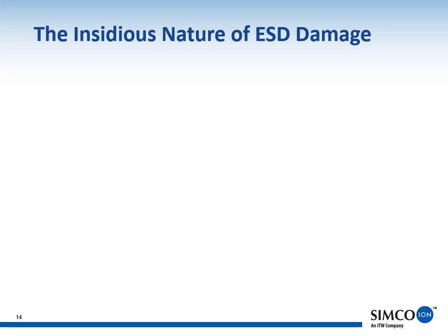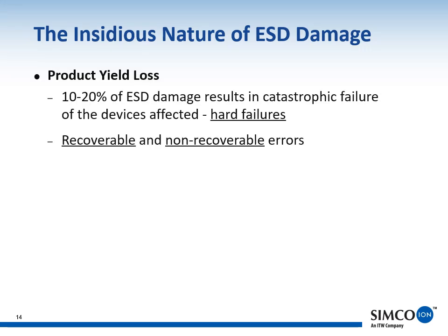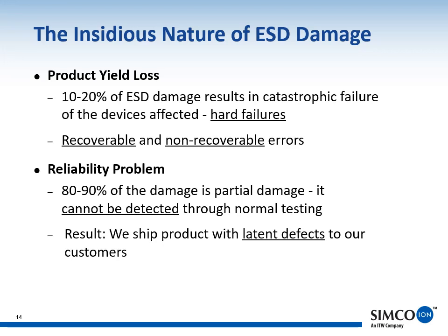The other serious problem with ESD damage is that only a small fraction of the damage results in catastrophic failures. Many times, the damage is only partial, and the part then fails later, possibly after it has been shipped and used by the customer.